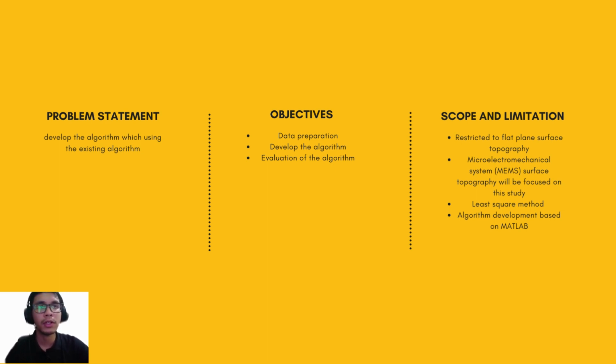Finally, the objective is testing and evaluating the algorithm by comparing the result with commonly used methods to evaluate its efficiency. In this research, it is limited to the analysis of the flat plane, which is the context of leveling micro electromechanical system. The least square mean method is used to level an area surface texture by fitting a plane to the surface using the least square method.